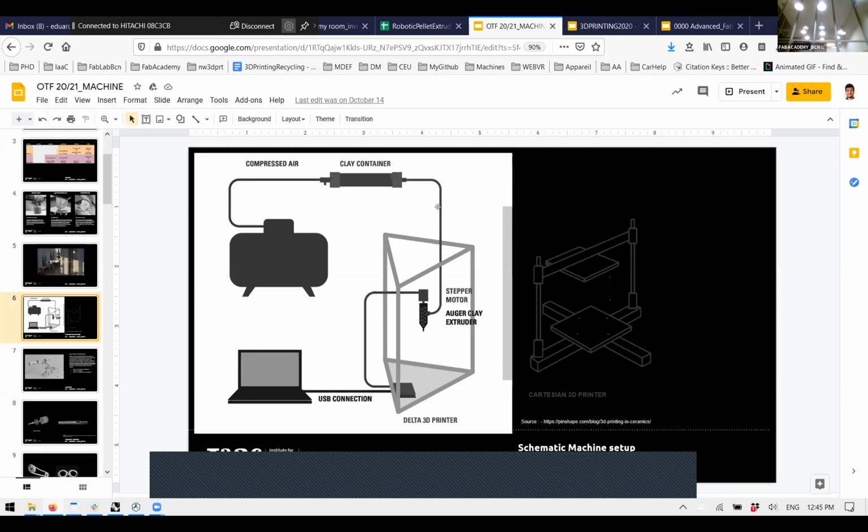And you can change this design. We make small modifications to match this printer. We have different models, and we can print different nozzles. For example, if you want, you can do a star nozzle, a little bit useless, but you can do it. This one, for example, is 3 millimeter. The bad point of this system is that when you finish, you need to clean it all the time, and it's super annoying. Actually, the worst part of paste printing is cleaning up the cartridges. Printing itself is super clean in general.